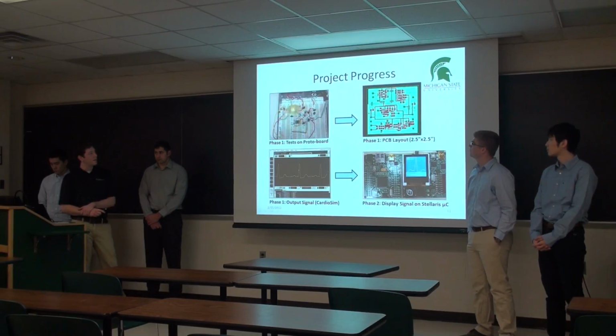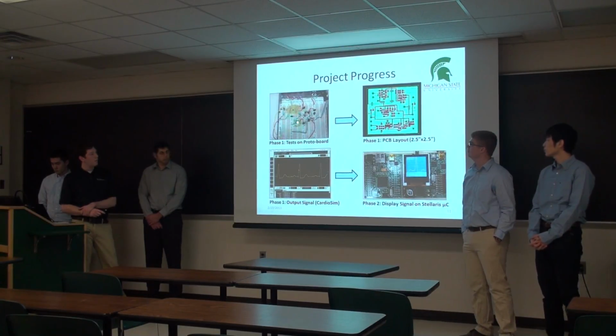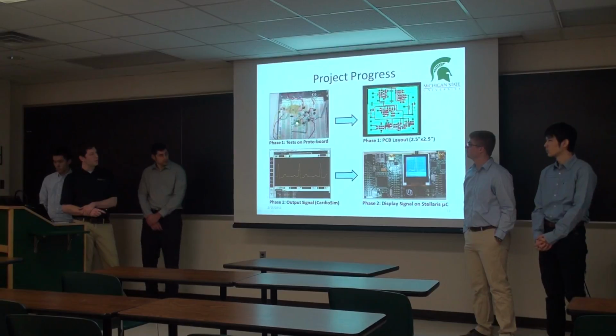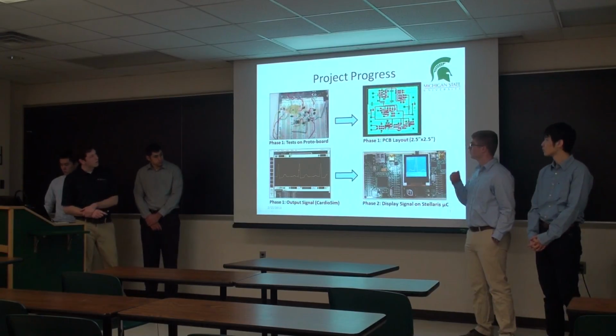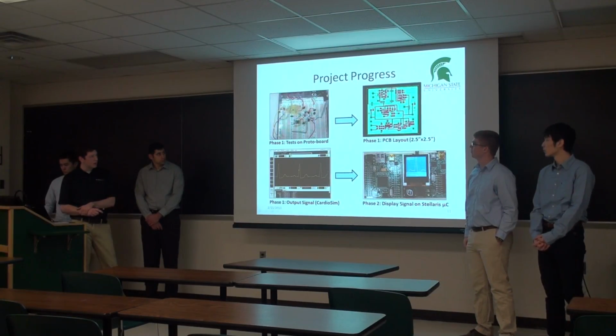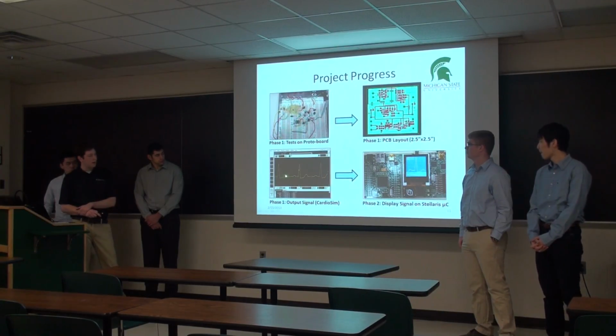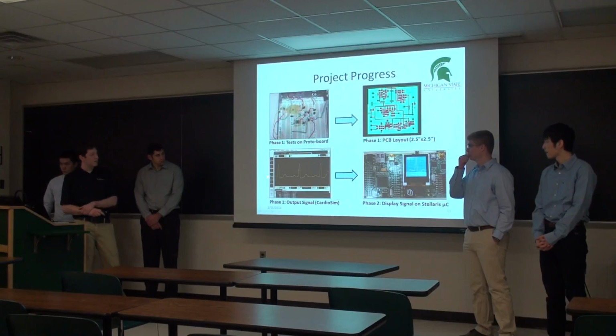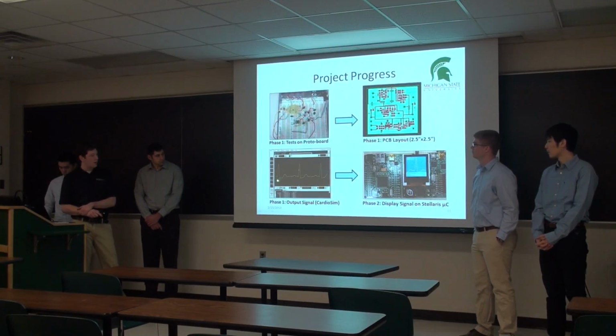So we have an INA333, one version of an OPA333 for the right leg drive, or actually 2 of them. And then we have just 2 741s, but this is pretty much our entire circuit, and we got it to work. This is the output from that circuit, getting a noisy signal from either the ECG simulator or the Agilent waveform generator.